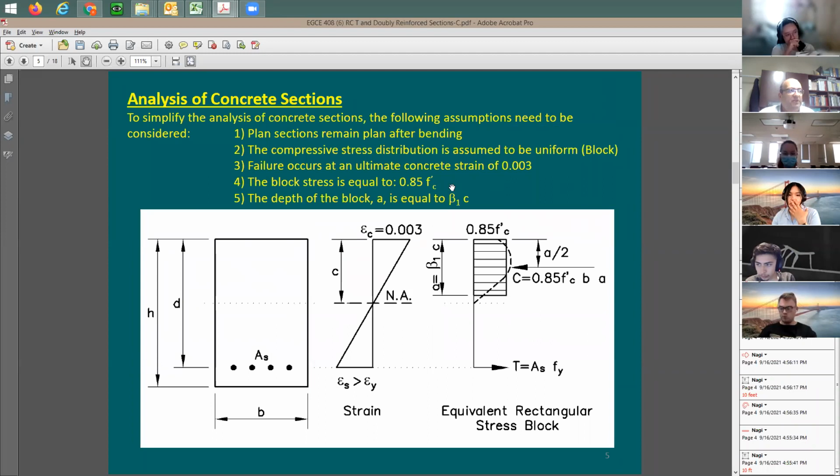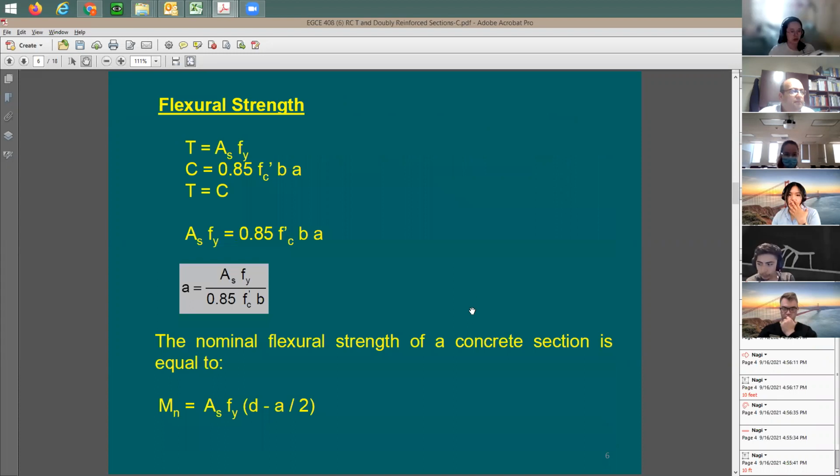When it comes to the design equations and analysis equations, they can be the same, nothing new. The difference is that in here, tension is going to be at the bottom, and on the top, in compression, you're going to have a flange. And the concrete section is going to be all of that. So we're going to have a larger compression area when it comes to concrete, which is going to help us out. About the equations for analysis? Same, no change. The same ones that we have used for the rectangular section.